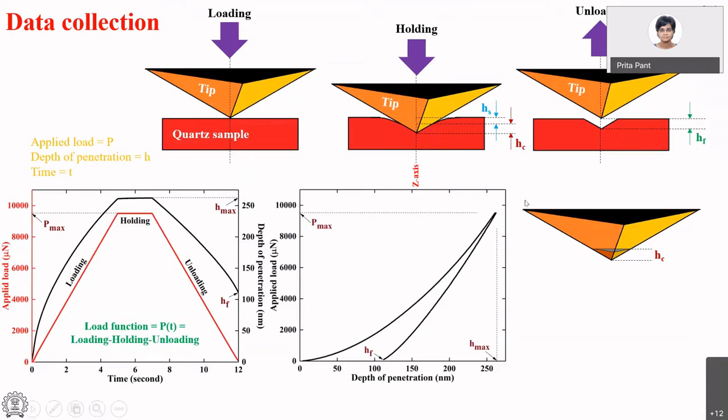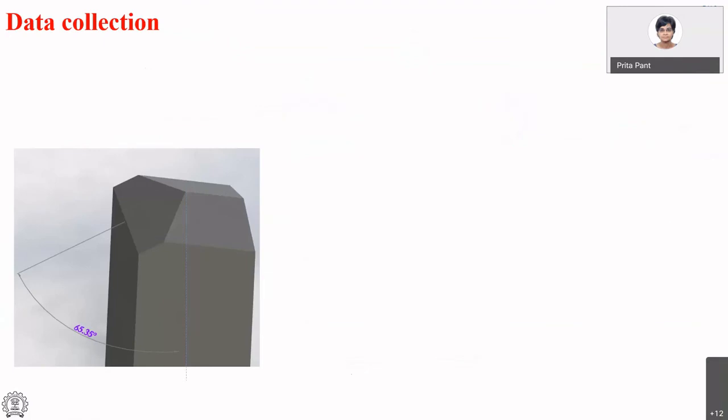Okay. So now if I could zoom in on that part, which is what is shown in the schematic here, this depth C, and cut out a cross section. Okay. That's the cross sectional area that I'm interested in. I'm saying that I apply a load P, and this is the cross sectional area of the imprint. So I'm going to repeat some of those things here, that this is what we are interested in, this cross sectional area. And remember, this is what my ideal tip looks like.